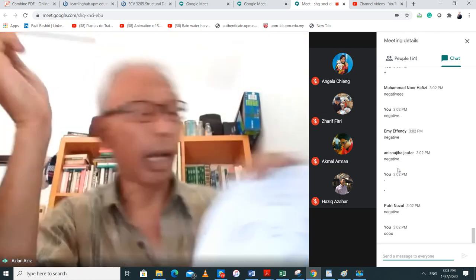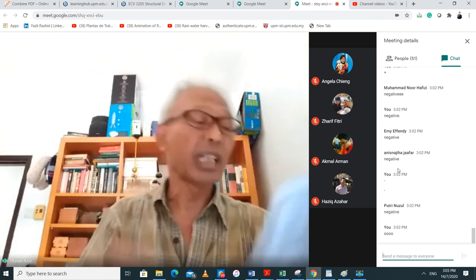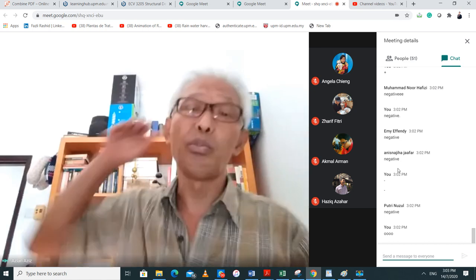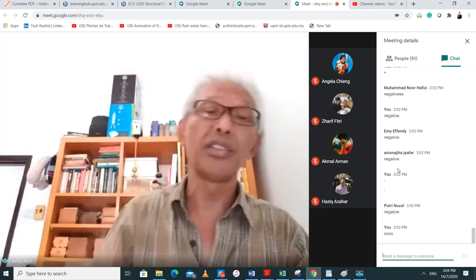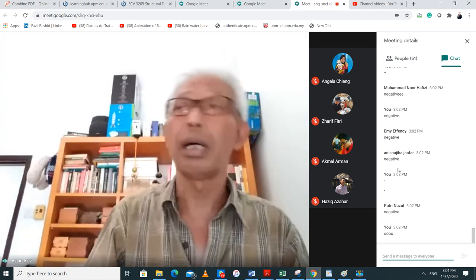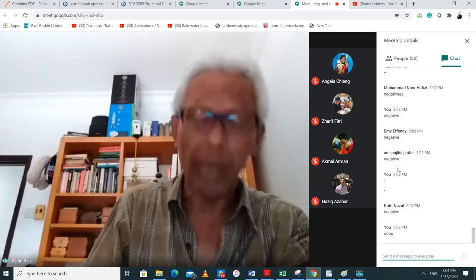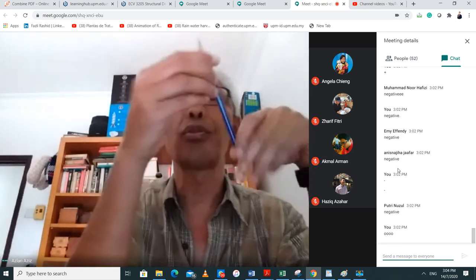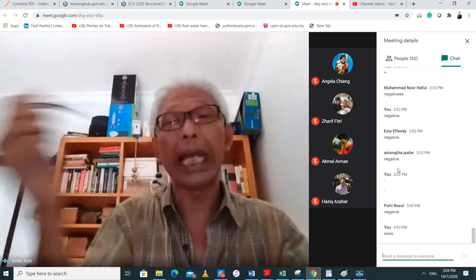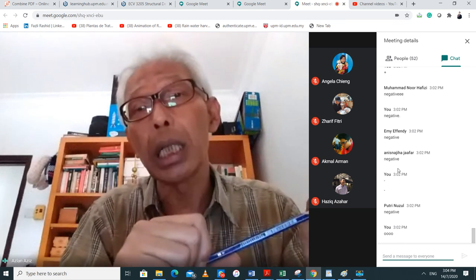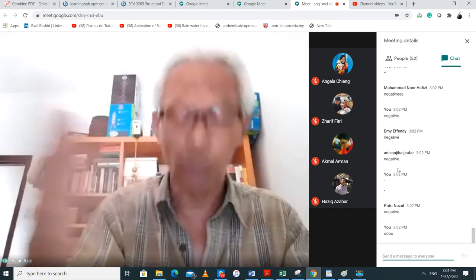Okay? All right. You notice that this part here is inclined. It's inclined because at the bridge, as your car gets onto the bridge, you give it a sudden jolt. So you also give a horizontal force to the soil. So you incline it so that you can resolve the forces in the horizontal direction, and you oppose the force that you give from the car. All right, that's additional knowledge. You don't have to remember that.